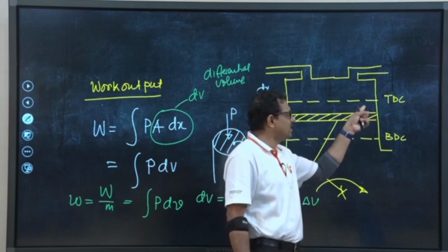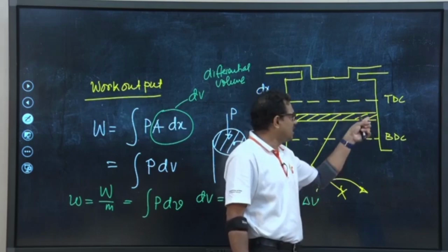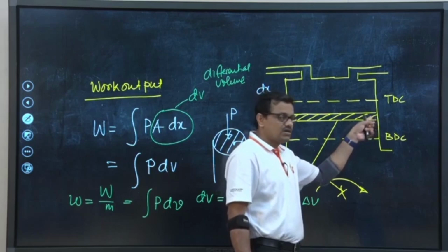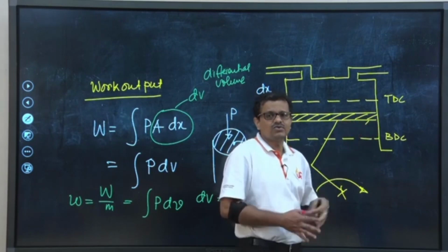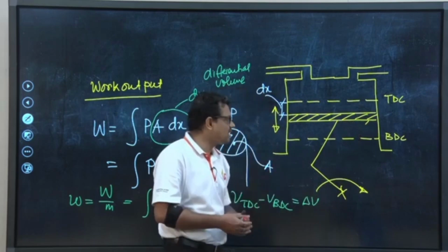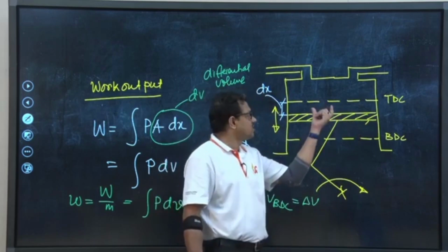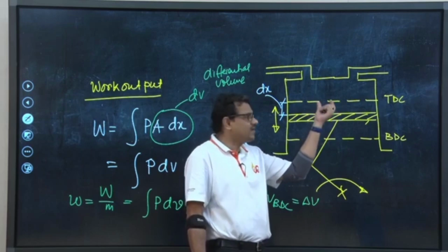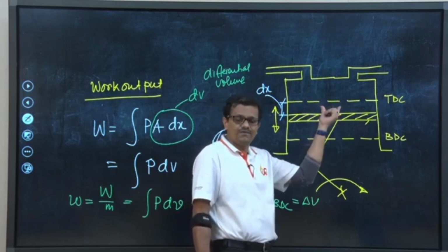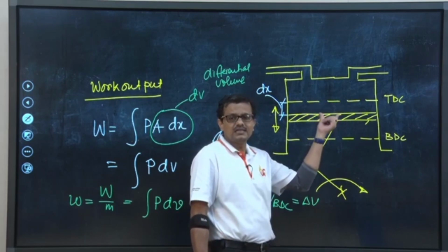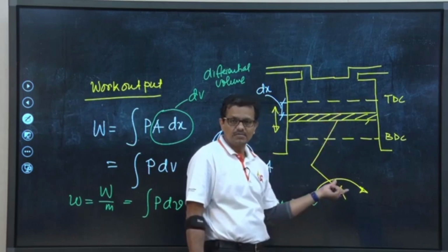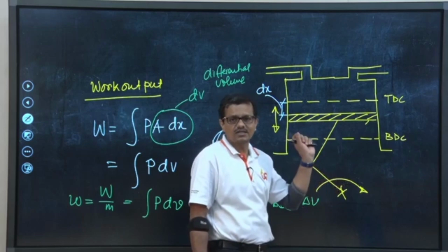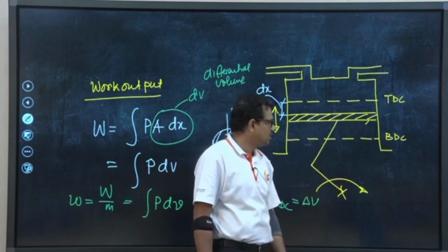So, the piston will be having to and fro movement, and frictional loss between these two mating parts will consume certain amount of work that is being produced. So, the work which is available on the piston face inside the engine cylinder is not available at the crankshaft, because the frictional loss is there.